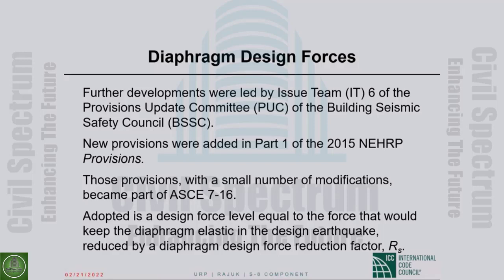One thing that one of them pointed out is that today you referred to ASCE 7-10 instead of ASCE 7-05. Was there any particular reason? I stated the reason. The building separation requirements that I shared with you are in ASCE 7-10. They were not in ASCE 7-05. So for building separation, I definitely switched. For the other portions, it does not make any difference whether it is 7-05 or 7-10, because things didn't change.